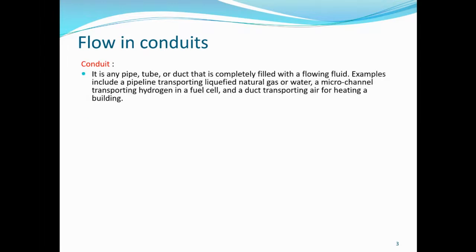So flow in conduit, and what is a conduit? A conduit is any pipe, tube, or duct that is completely filled with a flowing fluid. Notice this: completely filled. You can have a conduit that is not completely filled, and that is classified under open channel flow, not pipe flow.